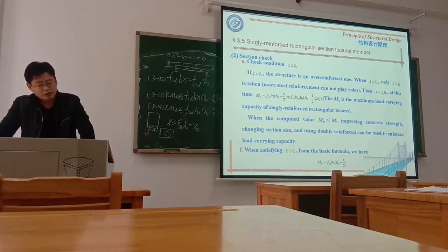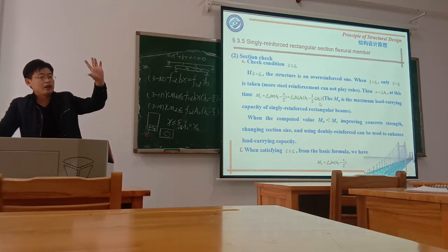If it is over-reinforced, for this situation, the load capacity we use this formula to calculate. If it is appropriately reinforced, the same formula, just the x differs. In the over-reinforced case, x equals xb h0, the boundary height.